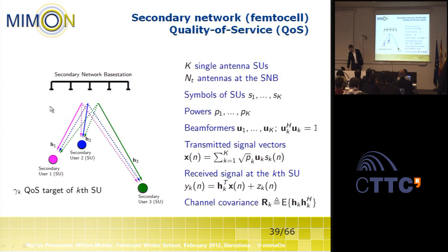We will have the transmitted signal multiplied with the respective channel vector. So this channel vector is denoted by H1 to HK. So it basically contains the different complex channel weights from the receiver of the femtocell user to the different transmit antennas. So we assume that this channel vector is known at the transmitter, be it from feedback,